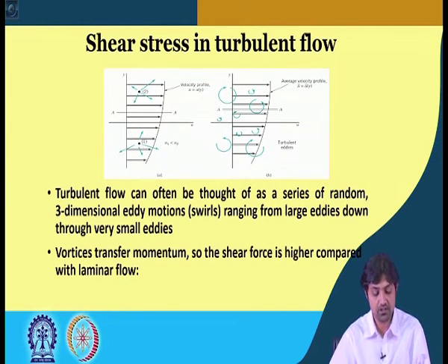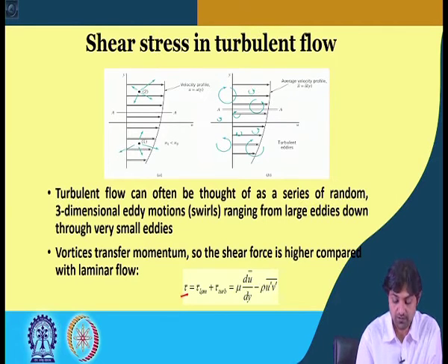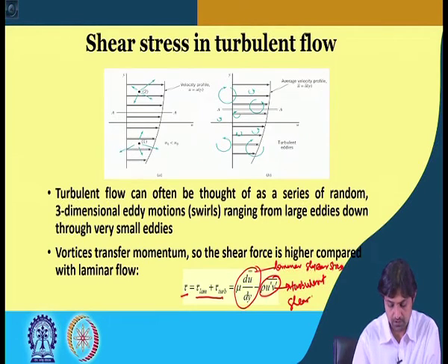These vortices transfer momentum, so the shear force is higher compared with laminar flow. In turbulent flow the shear force is much higher when compared with laminar flow. The total shear stress in a turbulent flow can be written as a combination of two things: shear stress due to laminar flow plus shear stress due to turbulence, and this is the laminar shear stress, and this is the turbulent shear stress.